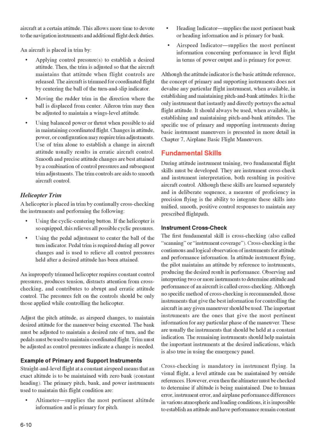Although the attitude indicator is the basic attitude reference, the concept of primary and supporting instruments does not devalue any particular flight instrument, when available, in establishing and maintaining pitch and bank attitudes. It is the only instrument that instantly and directly portrays the actual flight attitude. It should always be used, when available, in establishing and maintaining pitch and bank attitudes. The specific use of primary and supporting instruments during basic instrument maneuvers is presented in more detail in Chapter 7,